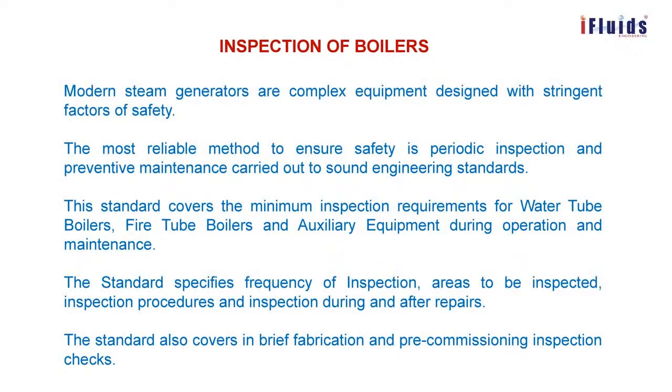So now today we are discussing inspection of boilers. Inspection of boilers has two or three stages. One is pre-erection, that is before construction. At each and every stage, we have to inspect each activity and whether the activity complies with the requirement. And after erection, testing of the boiler to meet the standards.